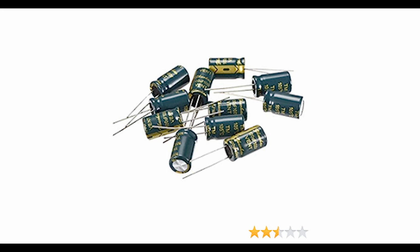Capacitance and voltage ratings. Polarized capacitors come in various capacitance values, ranging from microfarads (µF) to farads (F). The voltage rating indicates the maximum voltage the capacitor can safely handle without failure. It is important to select a capacitor with a voltage rating that exceeds the operating voltage in the circuit to ensure safety and reliable operation.